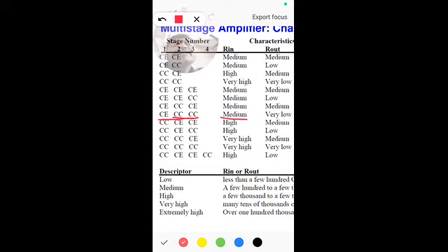In the second stage we have a common collector configuration, so the output impedance is very low, and the third stage is also a common collector amplifier, so the output impedance is very low. So when these two R naughts are very low, the output impedance is very low, and only one voltage amplification is possible, with the first stage.